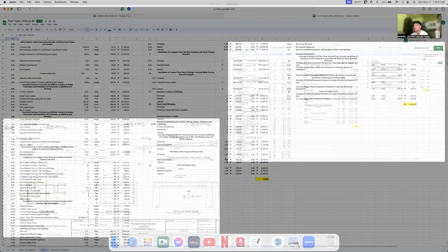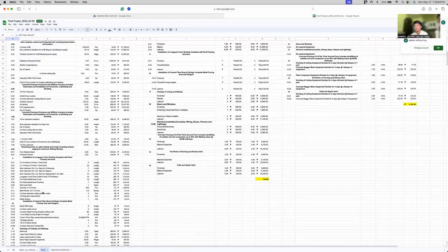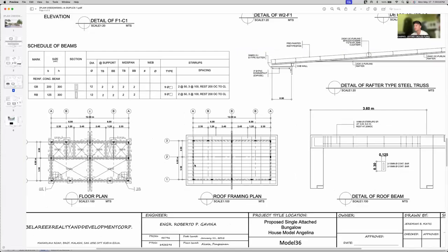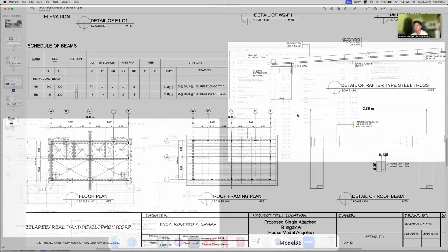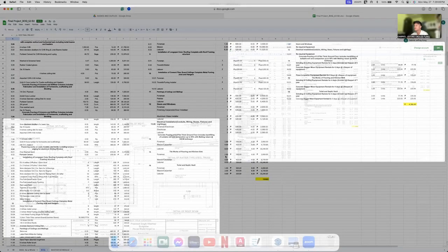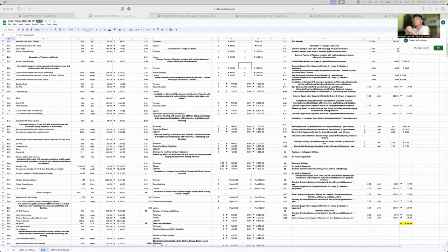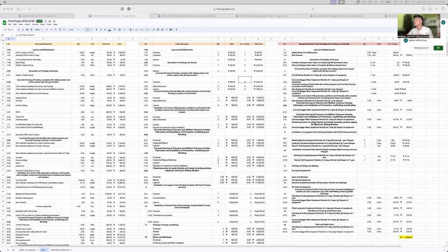I forgot the specific spacing, but with every intersection again, we utilized a blind rivet more or less, and then a cutting disc for metal as well as metal scissors to cut for the flashing and other materials, and then a metal drill bit in order for the rivets to be secured completely in the entire roof.